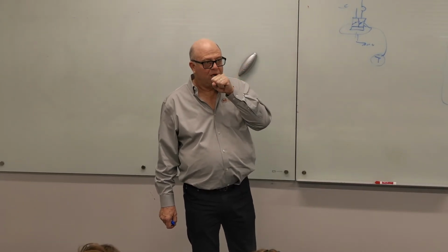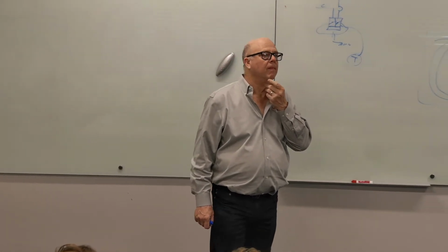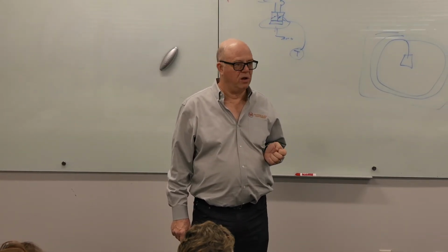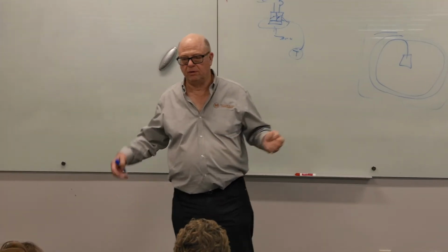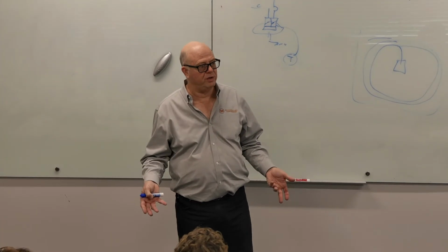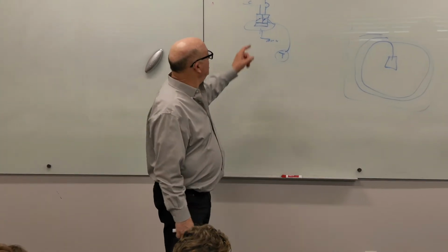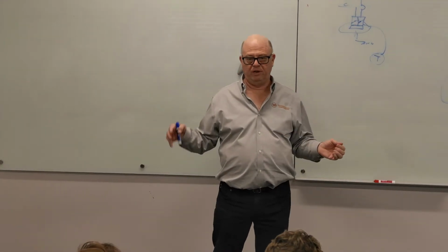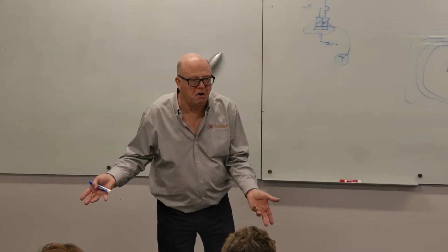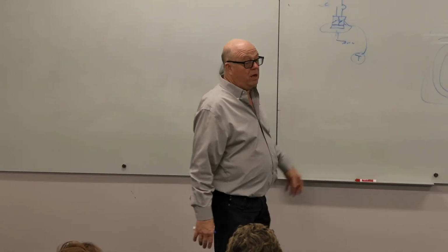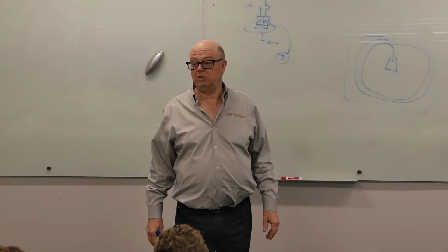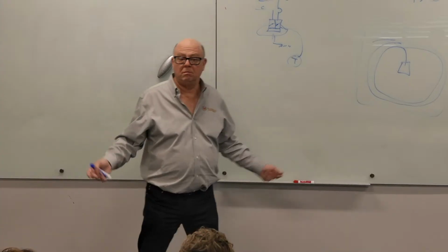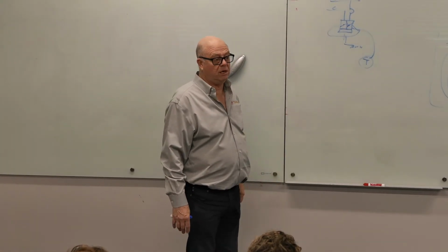But it will be interesting to see the track record of the heat pump boilers over the next couple of years. If they fall on their face and the public at large determines that they're no good, then I think you're going to see more fan coils and more dual duct, because they are more forgiving of having cooler heating water temperatures. On the other hand, if they're a wild success and there's no issues and nobody has any problems, I don't think we're going to be changing away from single duct VAV reheat anytime soon.